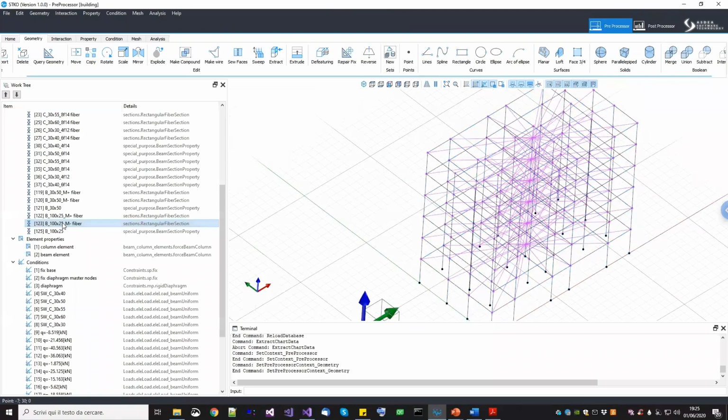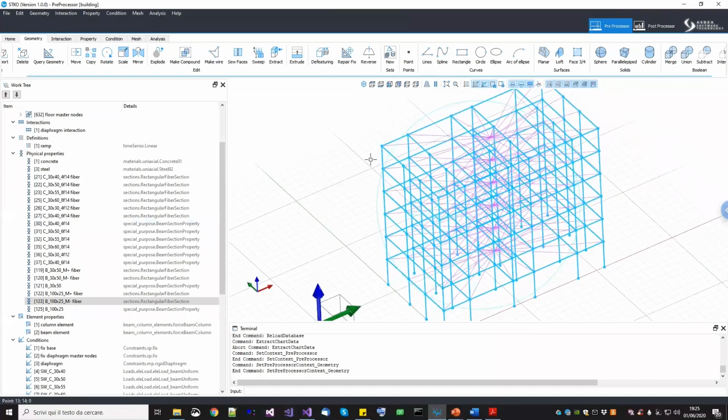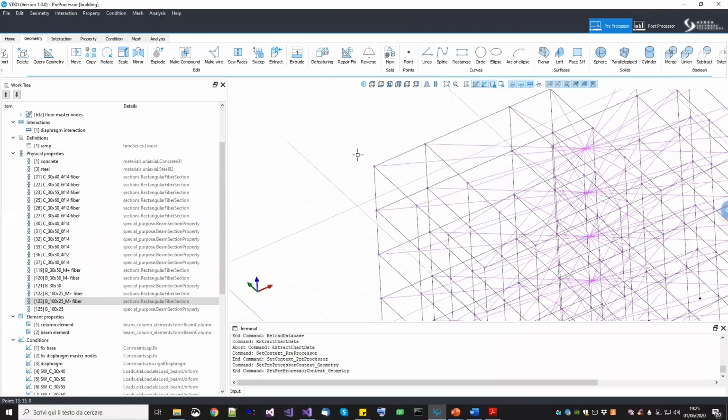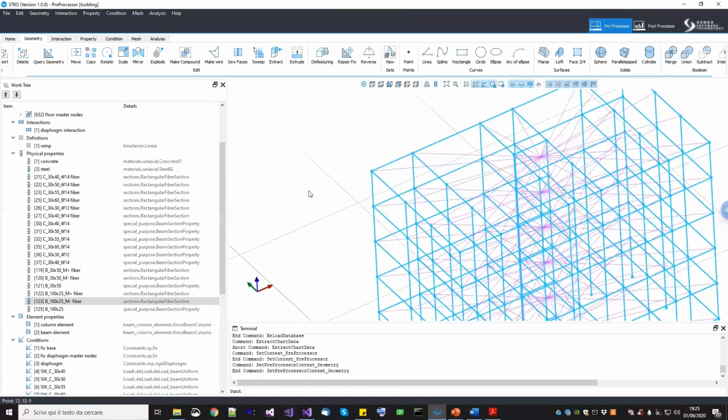Now, in this case, we created an automatism in STKO. You will see that it is very easy to create rigid joints here. You basically don't have to explode anything. You can keep your model continuous. You will assign some elements, some material to the vertices where you want a node, and there STKO will create nodes using the scissor model.